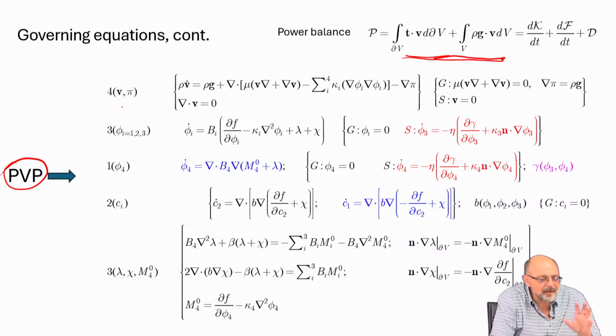And I nominally assign governing equations. You must have as many differential equations as you have variables. So for bookkeeping, I assign equations to variables, but they're all coupled, right? So the 4 equations of motion, which deal with variables, velocity vector and a pressure scalar, that's 4 scalar variables, are this modified Navier-Stokes. Now, this, and this, and this.